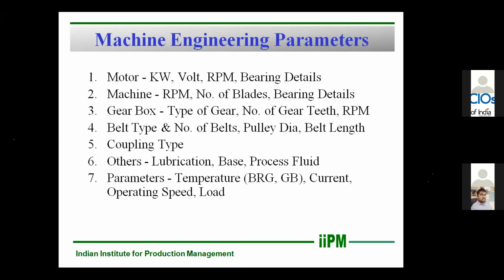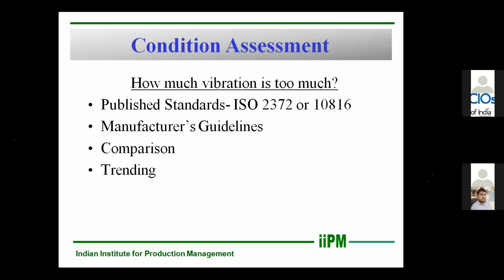Thank you, sir. These are the normal ratings you should know in order to diagnose the machine: motor kilowatt, RPM, gearing details, machine RPM, number of blades, bearing, gearbox, types of gear, number of gear teeth. All these inputs you need to know to diagnose a machine.